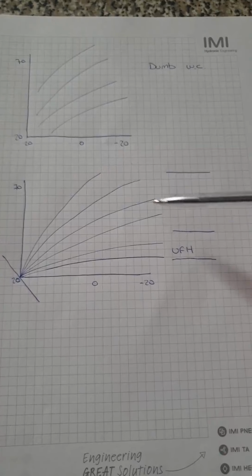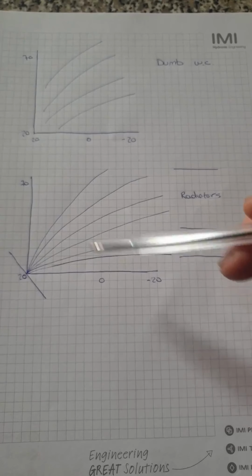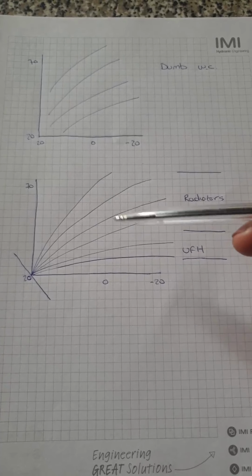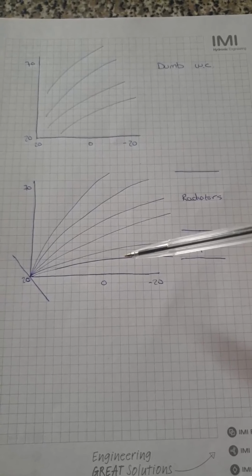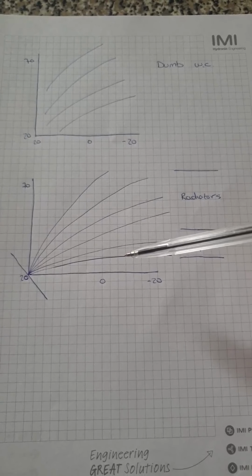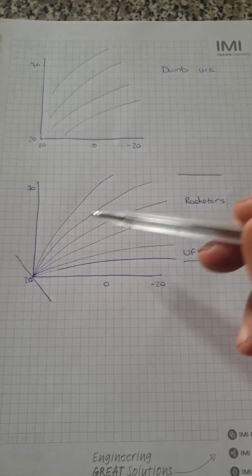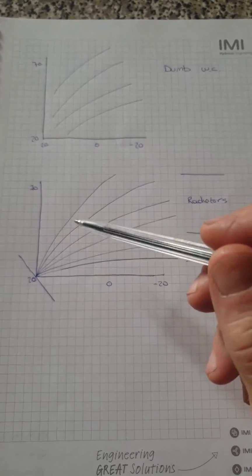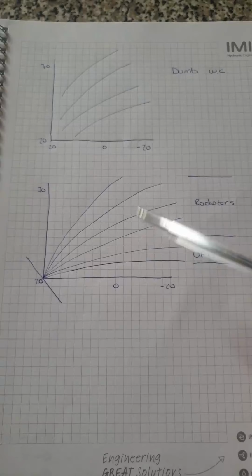So if we move over to the principles of the 200, they are similar principles to those used on the Vaillant boiler, and I think on a few of the other manufacturers now, Navien, ATAG, and Worcester, I think, follow a similar theory now, where you've got these adjustments, and some of them you can really reshape these curves. I think on the Worcester you can set multiple different positions across the curves.